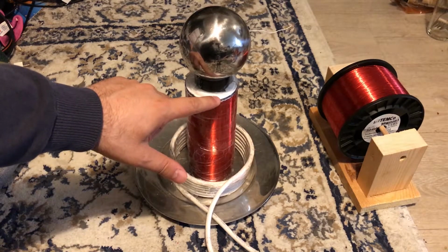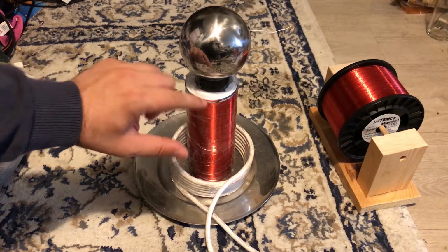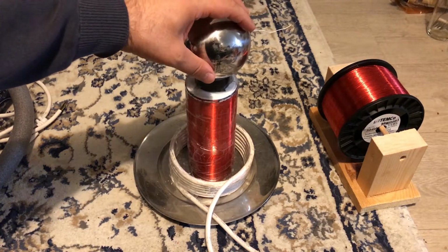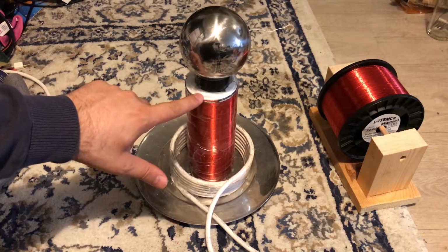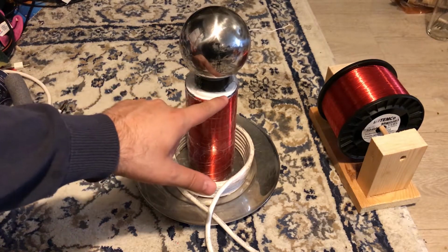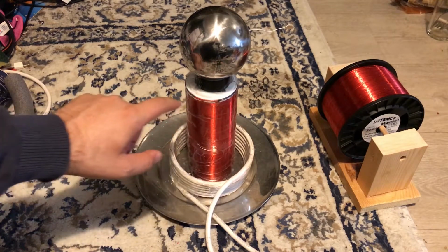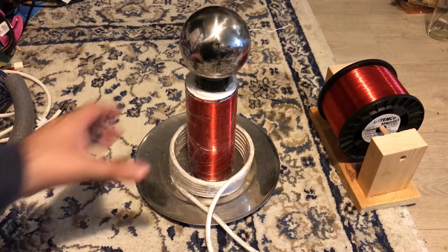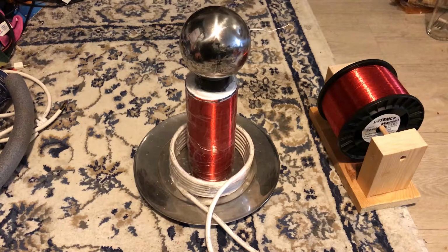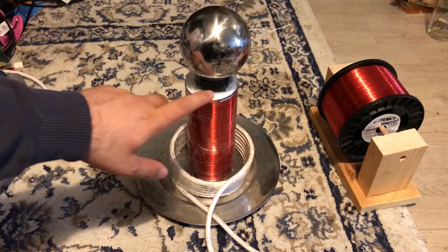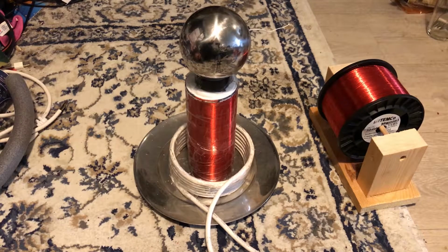But because here we have a sharp point, and this other part, which is the equipotential, is a little bit away from here, at these sharp points we will have a field enhancement, and basically the discharges can be initiated from this point. If the voltage goes very high, we will see discharges from these regions, and this is not good, because if we have many of these discharges, eventually the coil will be damaged.